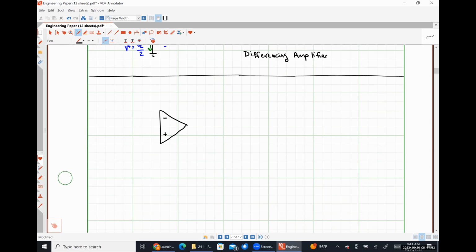All right, so both the integrating amplifier and the differentiating amplifier are really just special cases of a non-inverting amplifier. But instead of using strictly resistors, we are going to use an energy storage element. Now, I am going to derive these relationships using capacitors specifically, but we could just as easily implement these types of amplifiers using inductors as well. Okay.